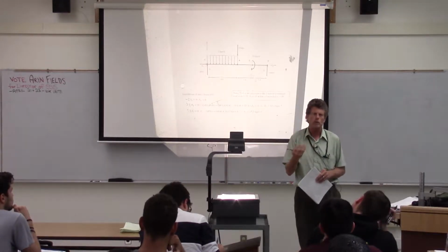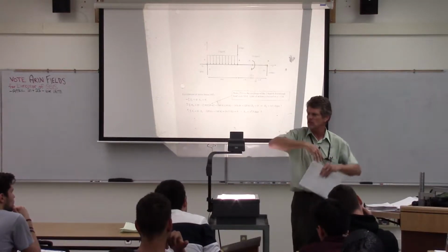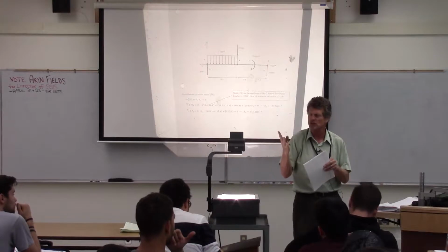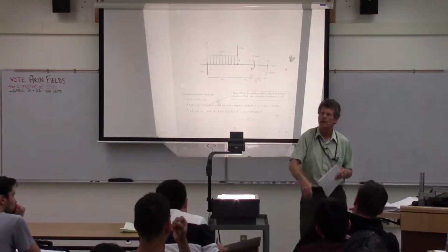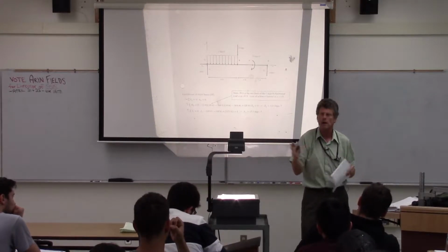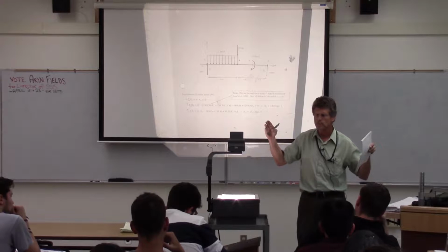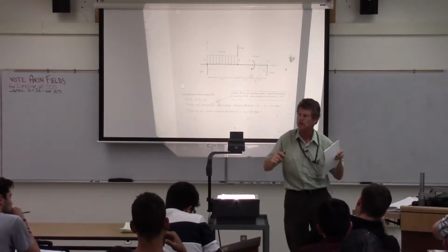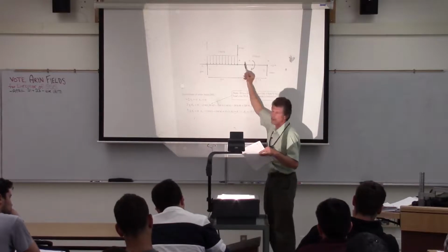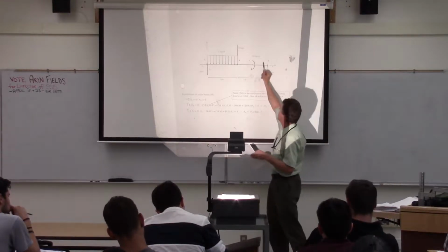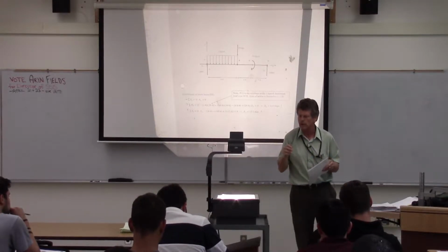And what we're going to be doing is creating shear and moment diagrams. What shear and moment diagrams are, are very nice ways for a designer to look at and say, I need to design for this much moment. I need to design for this much shear. And what we see is that it varies as we go across the beam. So we may not need to design for as much moment here as we would in the middle. And shear might be higher, and usually is, around supports because of those concentrated forces.